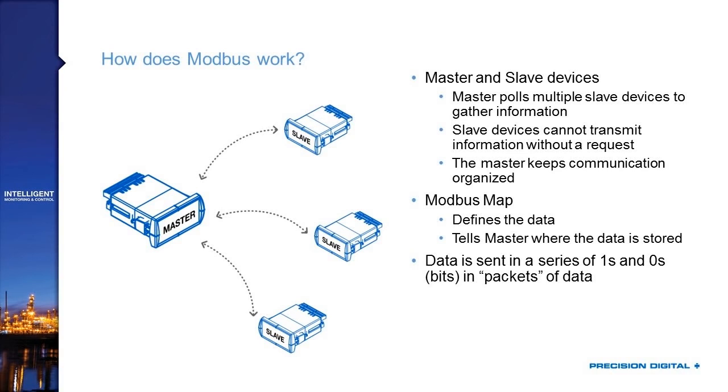When the master and the slaves are communicating, what are they doing? Well, they're using one of those buses we talked about earlier. You send a series of zeros and ones in a data packet back and forth to one another. And what the actual Modbus protocol will do is define what that data packet looks like. So many bits for the address to a meter, so many bits to give it the register, so many bits that hold a function like write this data to a register or send me back this other information, and then a bunch of bits for the data. It ends with some error checking. That format is really what Modbus is all about. It's defining how you read all those zeros and ones to build that complicated communication packet.